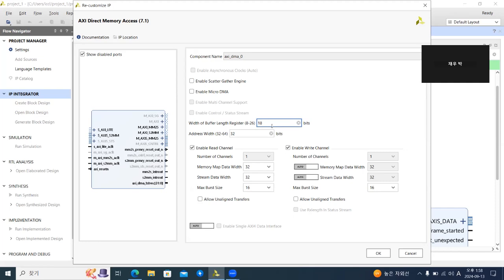And the first DMA we're going to use is to enable write commands. Write meaning DRAM writes. From the FFT accelerator's perspective, it will be data out. Data out from the accelerator and data written to the DRAM. So I will just disable the read channel for now.